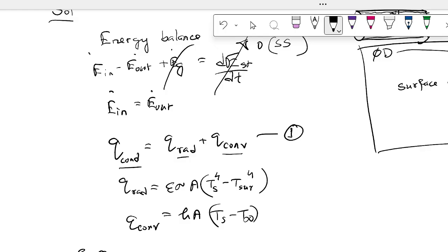It's a trick question. There's no unit for the emissivity, but there is the sigma unit. I gave it here: watt per meter squared Kelvin to the power 4, and then I have 7.85 meters squared as the area, right? And I have Ts as 423 to the power 4 minus 298 to the power 4, and these are Kelvin to the power 4, right?